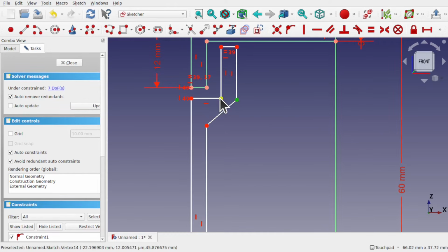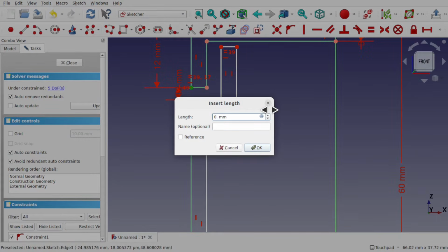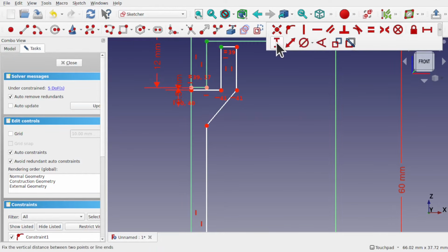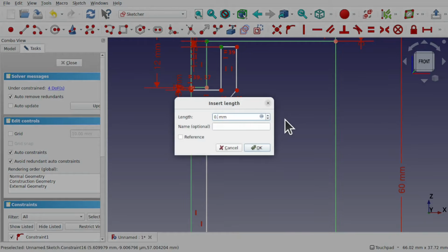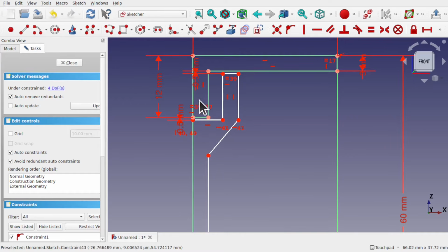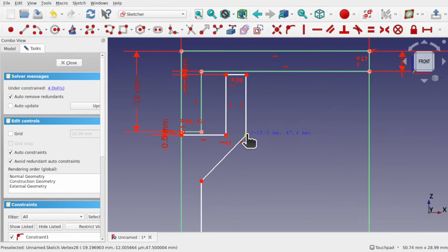And I may place these 2 points in line, place those in line, and we can put some tolerance in here. So I want a little bit of a gap, so this point and this point, and place some gapping in here of 0.5 millimeters, and do the same from these two, so this point and this point, height in here of 0.5. So that keeps these two sketches, well, these two pieces of geometry separate. So we've got this tolerance in here. This can still move in and out.